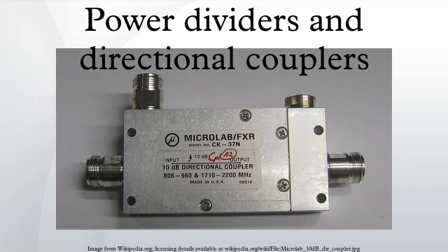If phase-matched lines are used for an antenna input to a 180-degree hybrid coupler as shown in Figure 23, a null will occur directly between the antennas. To receive a signal in that position, one would have to either change the hybrid type or line length. To reject a signal from a given direction, or create the difference pattern for a monopulse radar, this is a good approach.